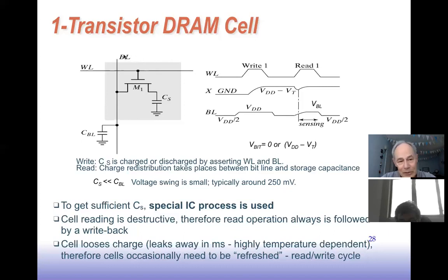With DRAM, sometimes this voltage on the bit line is boosted above VDD so that we get a good high voltage here. If we boost the word line voltage to VDD plus VT of this transistor, then we can get VDD on that bit cell, if that's important to do. And I think some DRAMs do that.